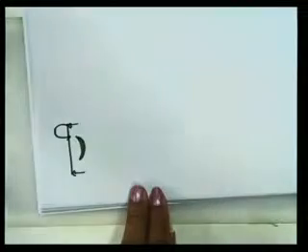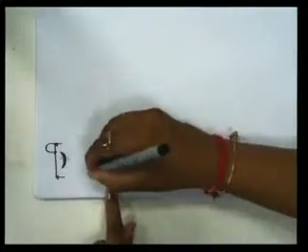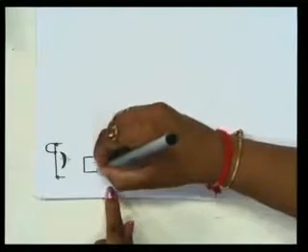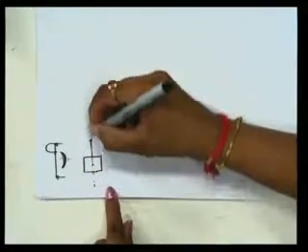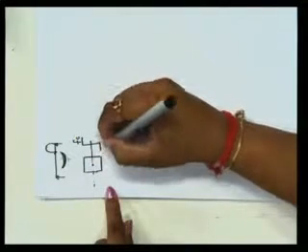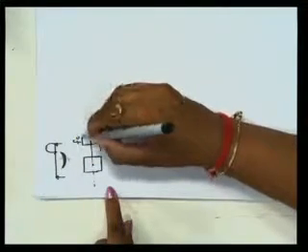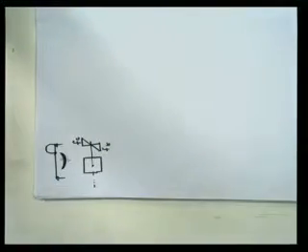So when the beam is bending in this particular manner, then the topmost layer is subjected to compression, and the bottom layer is subjected to tension. So now if I have a rectangular section and I want to draw a bending stress diagram, what will my bending stress diagram be? At the top I will have FC, that is maximum bending stress in compression, and at the bottom it will be FT, that is maximum bending stress in tension.